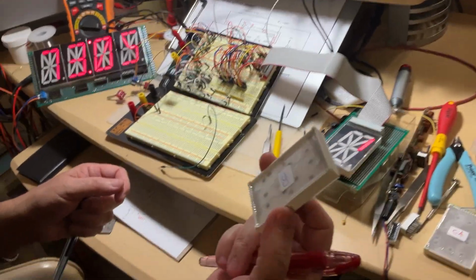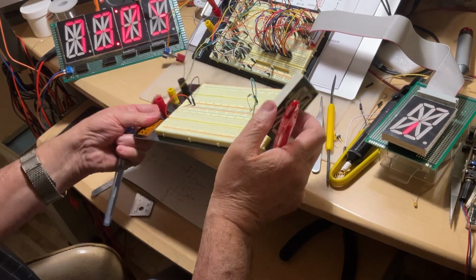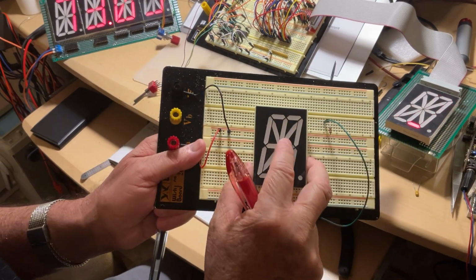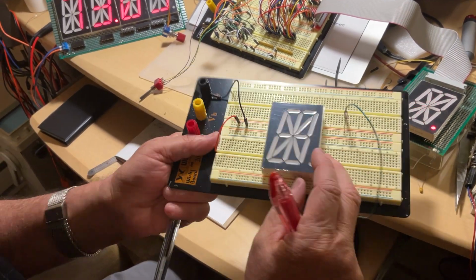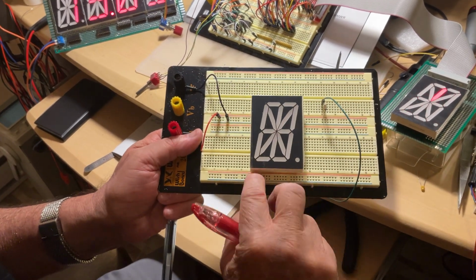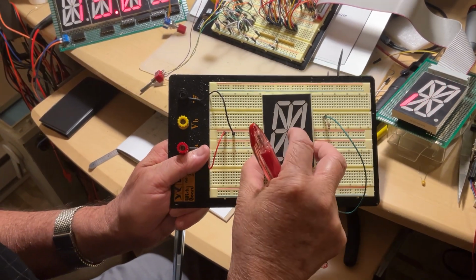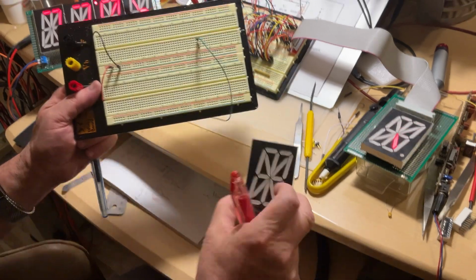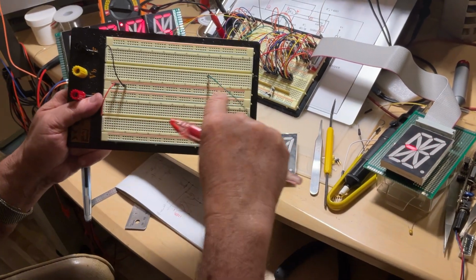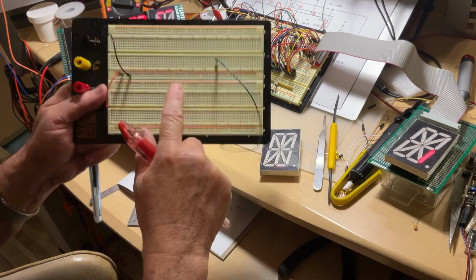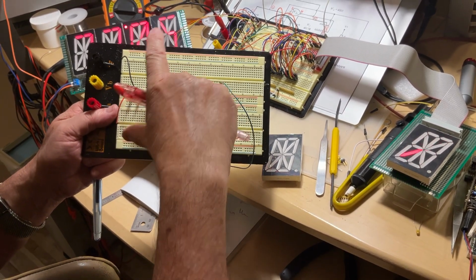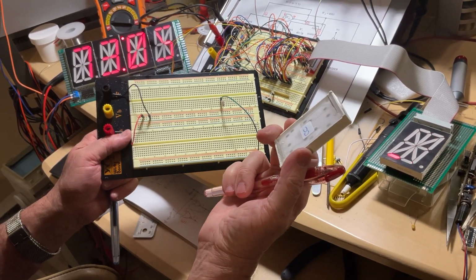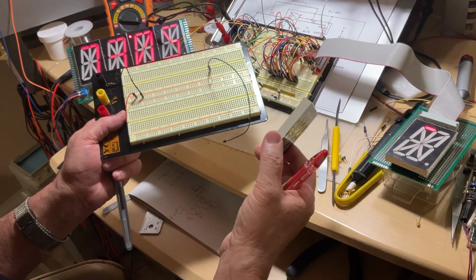because the size of this display makes it very difficult to plug in anywhere here. Anytime you try to plug it anywhere, there is no room remaining to take measurements around the terminals, okay? Anywhere you try to move it, you're going to have a problem. The only way you can overcome this problem is if you take 2 separate breadboards, not both of them assembled here as a double, but 2 separated ones, so you can keep them at a distance, and then you can plug this one half on one breadboard and half on the other breadboard, so then you can try to measure.